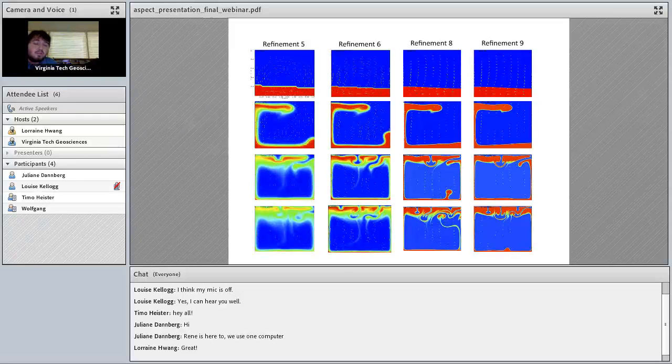And this can be attributed to the difference in the first panel. In the first row, you see that refinement 5's division between the 2 layers is made up of 3 horizontal boundaries that step down to each other. Refinement 6 is made up of 4 horizontal boundaries that all step down to each other, and it changes by mesh refinement. So these discrepancies occur because the mesh is being changed, which is not desirable, and we'll go into how to fix that in just a moment.